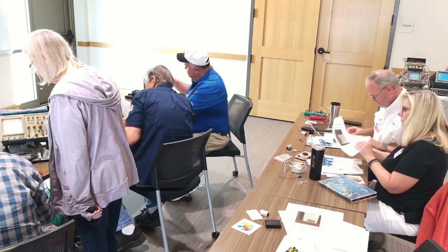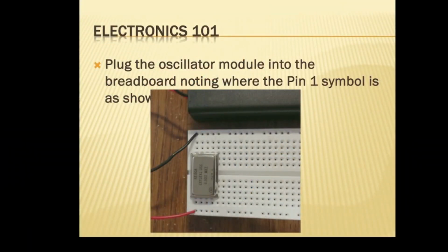Now, we'll take the thing over to the scope. Put ground on here, main probe on here, turn the power on, and we should get a 4 megahertz signal out of it. As long as it doesn't blow up. Hey, we're not gonna let the smoke out, I hope. Let's go see it. Grab that thing and just take it over and check it out.